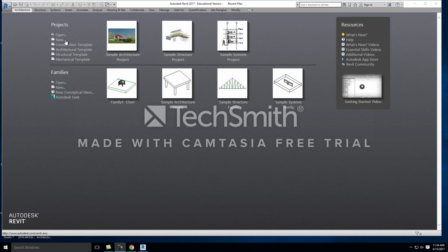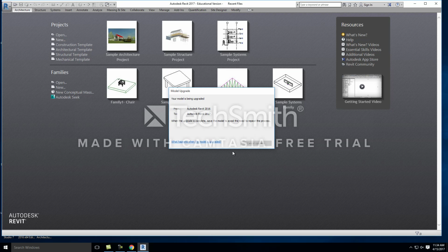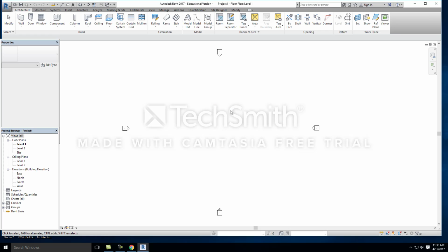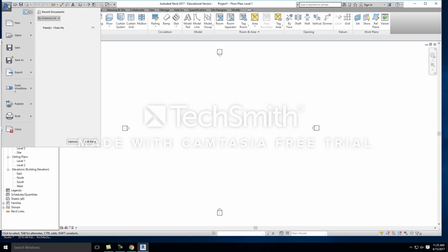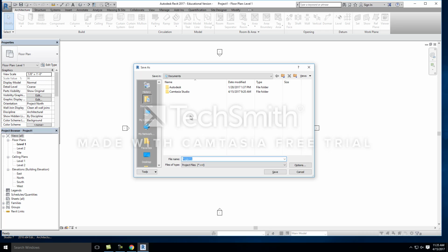Okay, so we're going to click on projects, and we're going to go ahead and go to new. We're going to click on architectural template, hit OK. We'll let this upload. All right, we have our new project. Let's go ahead and save this to our thumb drive right away. Let's save this as our new.